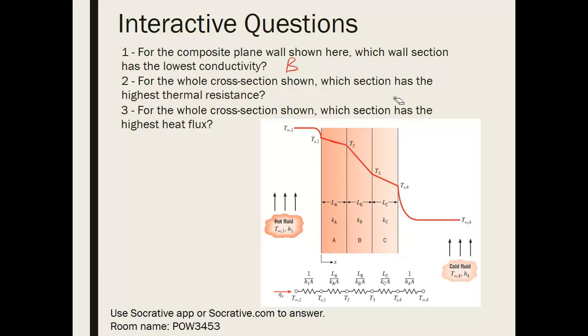One way of thinking about this is a material that's not easily conductive. You're going to see large temperature gradients because it's really hard for the heat to penetrate through that surface, so the temperature drops quite quickly. You can see this if you put your hand on the outside of a freezer, it might feel a lot closer to room temperature, whereas on the inside it's going to feel freezing. So there's a very steep temperature gradient through that freezer wall, because it's an insulating material with a very low thermal conductivity.